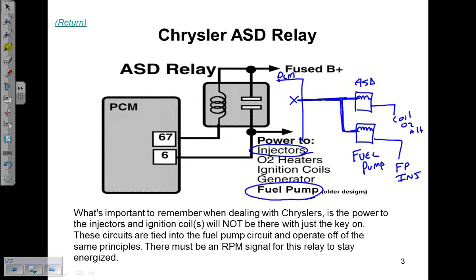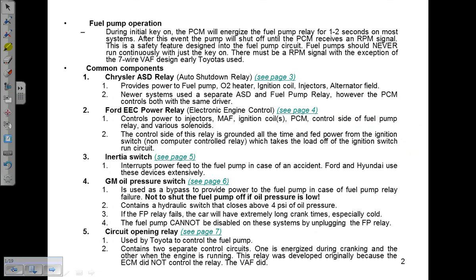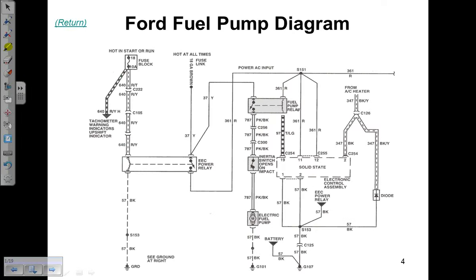So why did I pick this one? I picked this one to show you that variable with the ignition coil with a no start diagnosis. And I've seen other manufacturers do the same thing. Just be aware of it. As far as the Ford EEC power relay, and that stood for electronic engine controls. Let's go down to that figure on page 4.